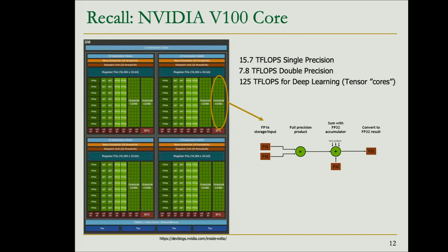We are not working with single precision or double precision floating point operands, but with half precision. This is 16 bits to represent the floating point number. It is a very common practice in deep neural networks, because this precision is more than enough to do training and inference in neural networks. And you can have what you see here with this mixed precision, because the input operands are 16 bits, but the output is 32 bits, or you can also have the output with 16 bits.